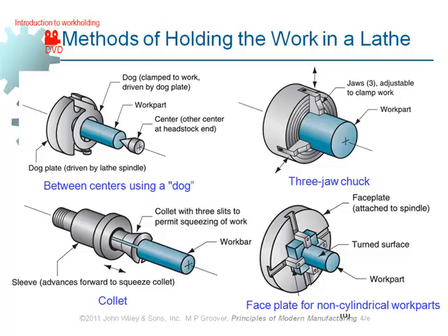That's important, right? Sometimes you have got a very rough and inaccurate external surface, which is not a good basis for actually locating the part. So you don't want to make use of that rough or inaccurate surface. You can make two holes at the two ends, and then make use of the two holes. So whatever you produce will be centered according to the central axis of the part. That's important. Okay?